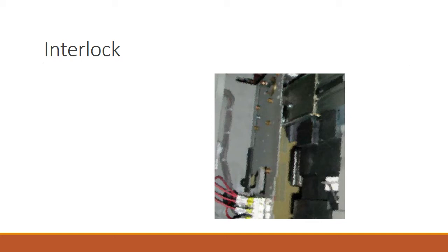Interlocks may be adapted to practically any form of switchgear, regardless of size or rating, due to their simplicity of design. The most typical application is to prevent paralleling of incoming power supplies, which is accomplished by interlocking the bus ties with the incoming feeder switches.